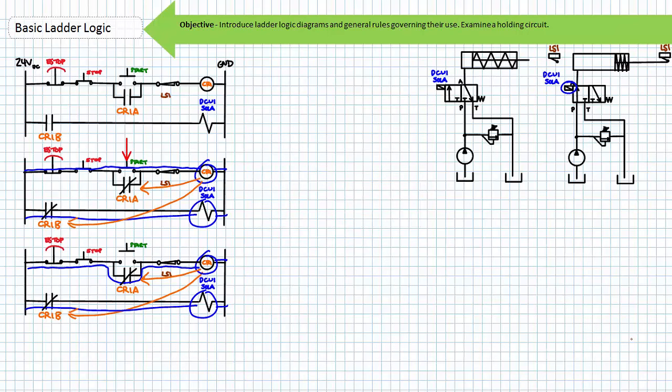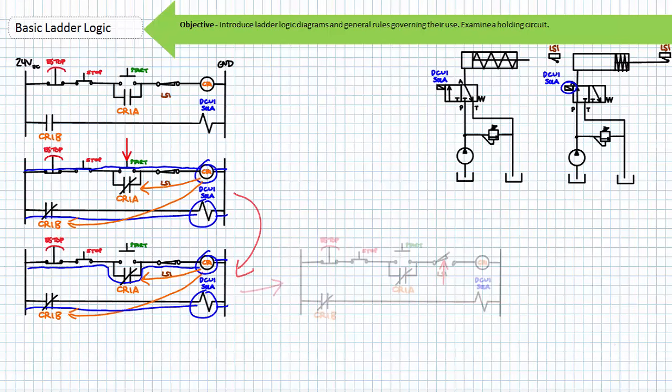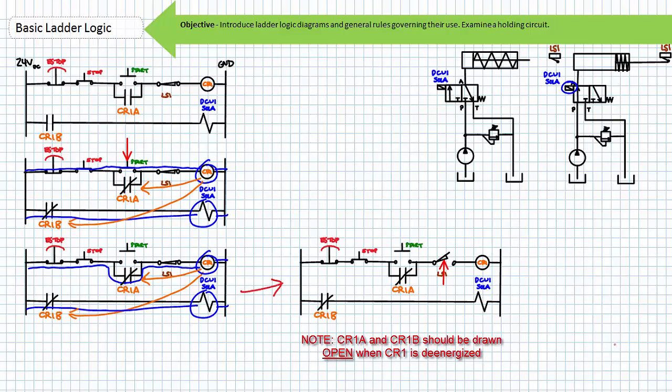This limit switch has in effect created a one-cycle reciprocation system. One-cycle reciprocation means that when an operator presses and releases the start button, the cylinder rod fully extends, strikes limit switch 1, and then automatically retracts, marking a complete cycle without the attention of the operator. If at any time an operator wanted to stop the cycle mid-stroke and retract the cylinder, they can press the momentary stop button. This returns the system to its go state, ready to initiate another extension. The e-stop, in contrast, would be for dangerous situations, necessitating not only a stop mid-stroke and retraction, but also a complete disabling of the system until such time the e-stop is reset.